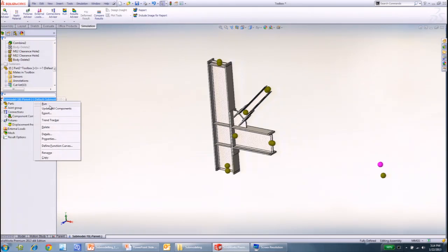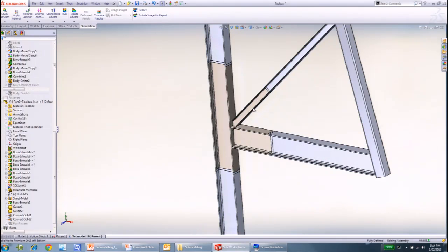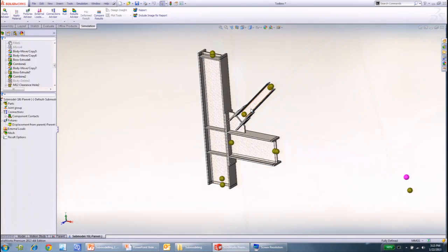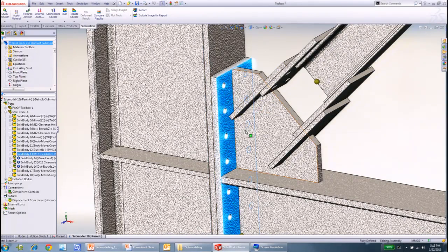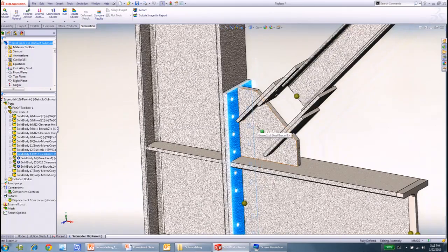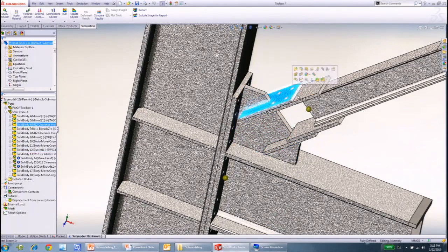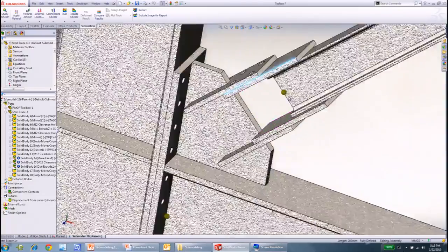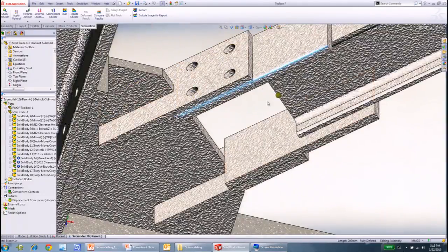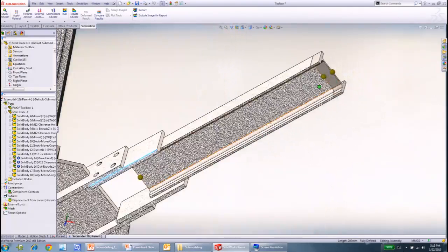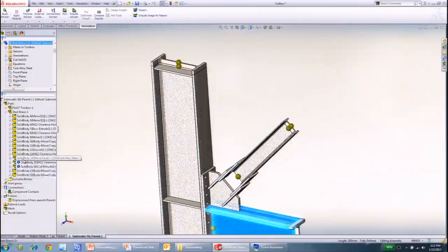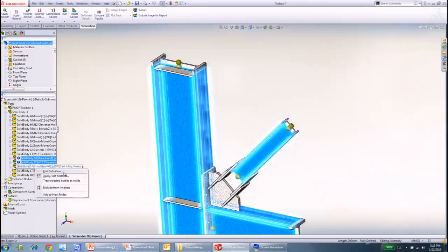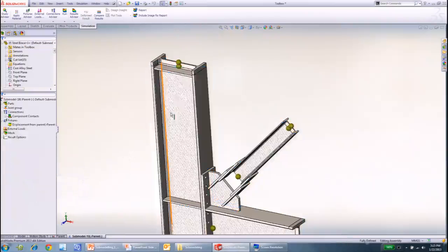So I'm going to come back to the submodel and just update it to make sure everything was updated. And you'll see that now I've added the plates. You can have fasteners, but I'm going to replace it with bolt connectors inside simulation. It has the gusset, it has the plates, which again are bolted. Right now I'm going to run 2 studies, one with just the bonded, so everything gets connected to the boundary nicely. And I'm just going to come back here and make everything solid because I don't have to analyze the whole model, so I can go fine.